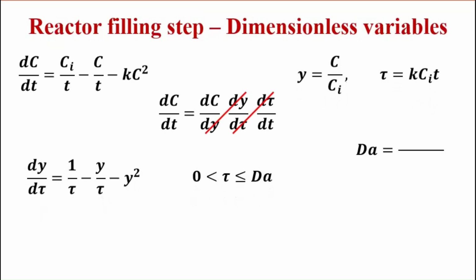The dimensionless parameter Damkohler is actually a measure of the reaction rate of ethyl acetate relative to its transfer rate in the inlet feed stream. In simple terms, if we want ethyl acetate to have the time required to react in the reactor, then it must have enough time to reside in the reactor. Therefore, we cannot expect the inlet feed to enter the reactor quickly and be converted into product immediately. To produce more product, it is necessary for the materials to spend more time in the reactor.